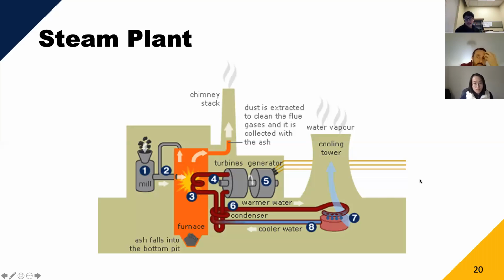Oh, okay, I see a comment here. So there's also heat exchangers, so the steam and the cooling water do not mix. Yeah, exactly. So that's this part here. So the heat exchangers here again. So like this loop is a closed loop. So none of the water that's going through the turbine is going to be mixed with any of the cooling water, which is important, right? Because you don't want to send impurities through the turbine.